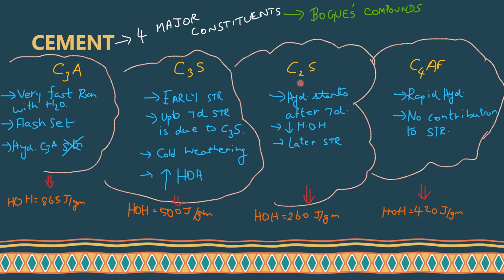And next is your C2S, dicalcium silicate. Here the hydration starts only after the 7th day. Here the heat of hydration is low. Here later strength is contributed, which means, as we have already seen, hydration starts only after the 7th day. So from the 7th day till your 20th day, the hydration process gives your later strength.